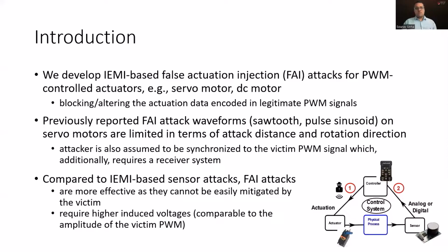In our work, we overcome these limitations. Our attacks work at larger distance, can rotate the servo in any direction, and don't need to be synchronized to the victim PWM. Also, compared to the IEMI-based sensor attacks, i.e. the attacks at point 2, the FAI attacks are more effective as they cannot be easily mitigated by using, for example, robust state estimators. However, these attacks require higher induced voltages that are comparable to the amplitude of the victim PWM.